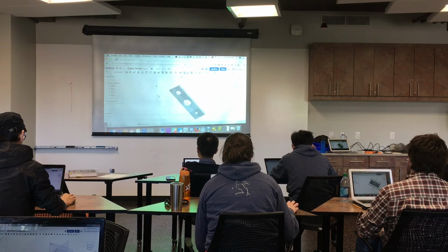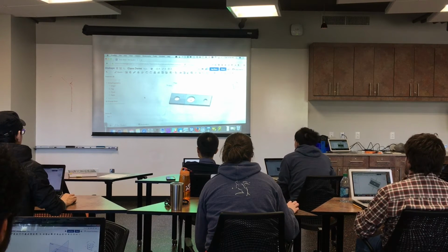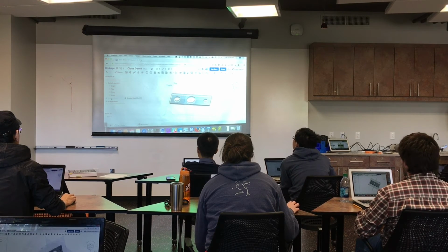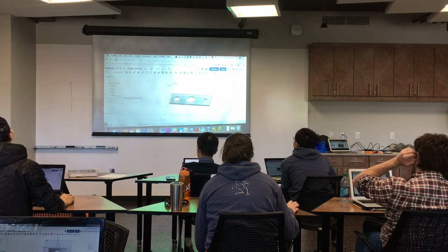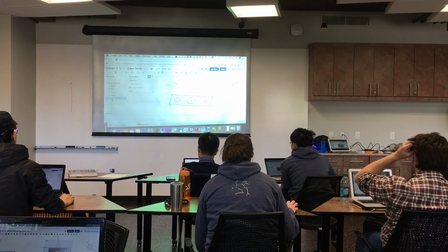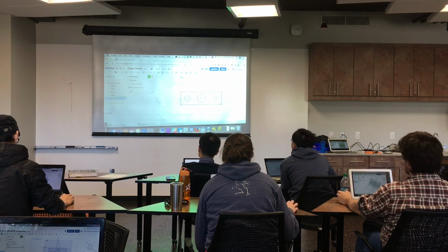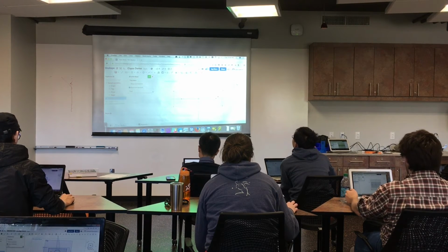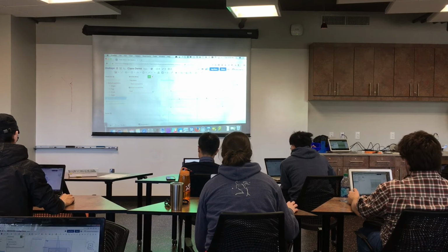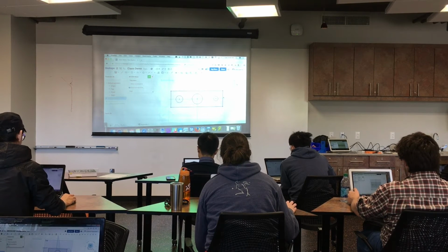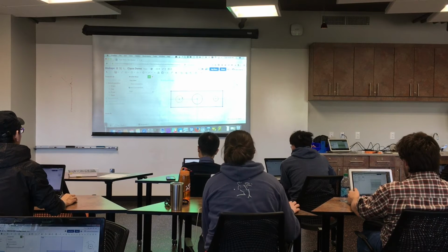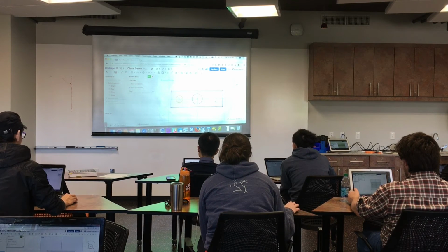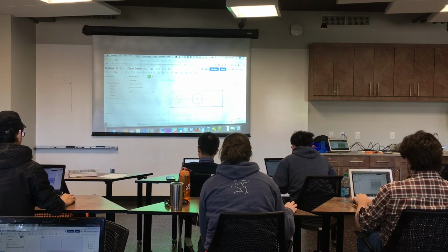But all right, so now we've got this. Here's the nice thing about these kind of tools. Go back here to the bracket base sketch, double click, and we'll hit in. So now we're back to our 2D sketch, and we have some work to do. So first, click the two circles here, so that they're both orange.